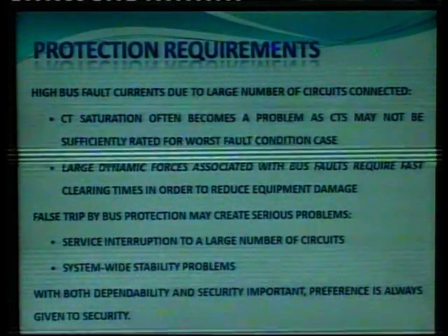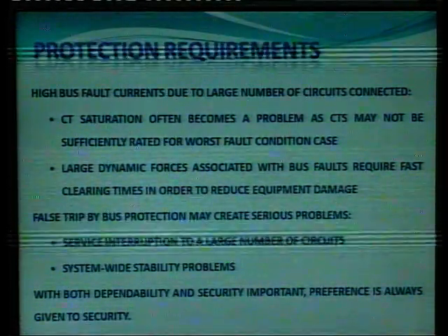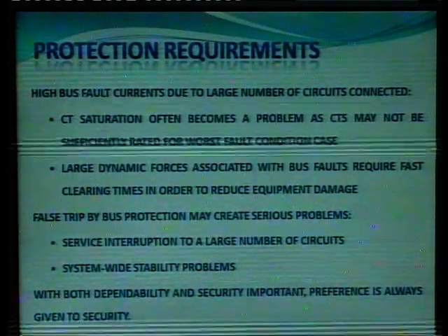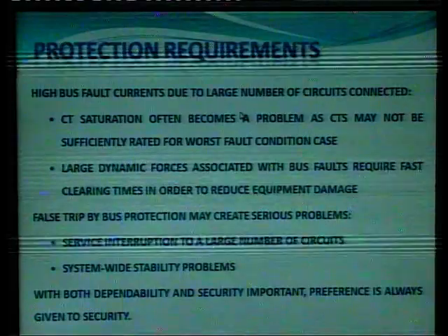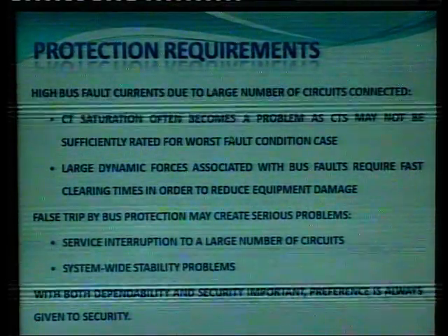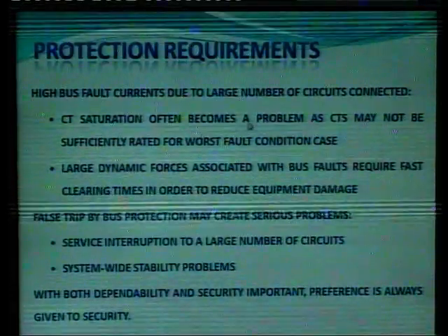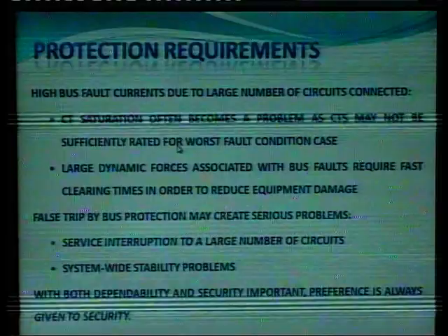As we know, a bus bar is a kind of node through which various connections can be made. So, there may be a number of CTs connected to that bus bar, and there may be a problem when those CTs do not have the same ratio. So, this will become a major problem.